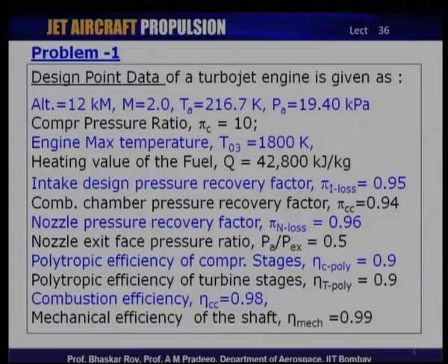Polytropic efficiency of the turbine stages is given as also 0.9. The combustion efficiency is given as 0.98, and the mechanical efficiency of the shaft, eta mechanical, is 0.99.